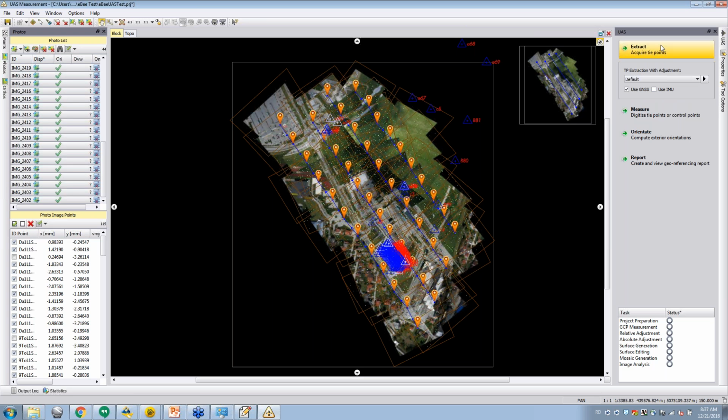This is just a sequential, simple workflow. You can, again, actually measure ground control points first. The more advanced you become with UASMaster and the more familiar you are with your data, you can actually set your own workflow, which is very nice. But for the beginner, this is a good workflow. We suggest that you stick with the default, and that is the half resolution, the resolution being 1:1 for full and 1:4 for low resolution on the matching ability. For bad images, you would use a low resolution. And then if you have GNSS data, this is pretty much using it as, I guess, a weight in the calculation. If you do not click it, it still needs those initial estimates, but it will not use the weighted estimates. We'll leave that on for this data.